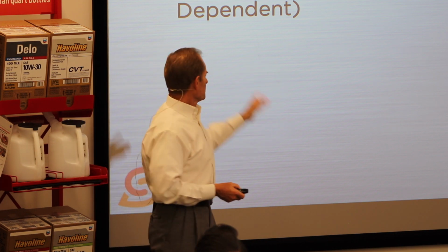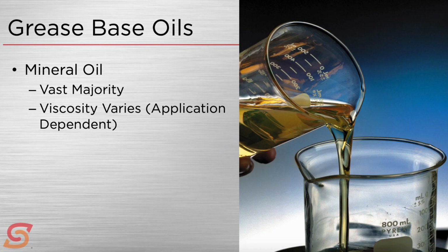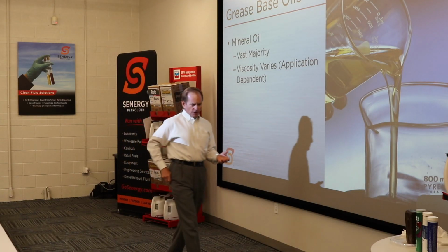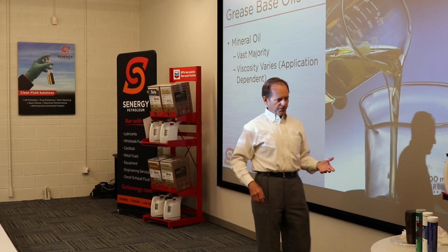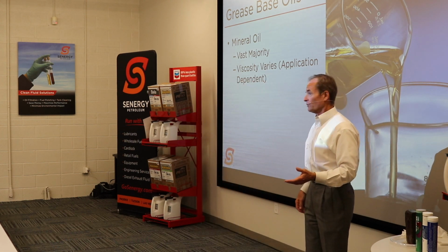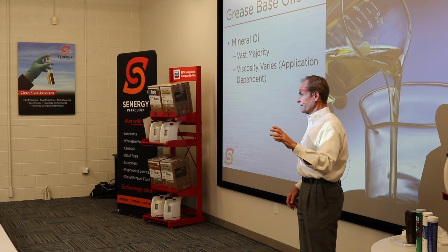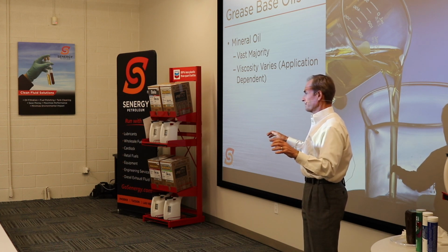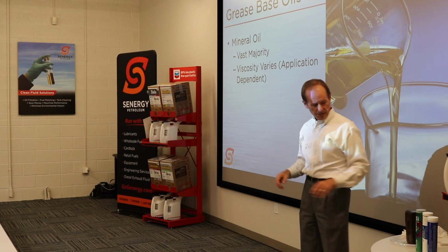What does make a difference is the viscosity of that oil, okay? Because you can make a grease, remember it's an oil plus additives plus the thickener, out of an oil that's thinner than diesel fuel, something very thin, or out of an oil that you can barely pour at room temperature, or anything in between.